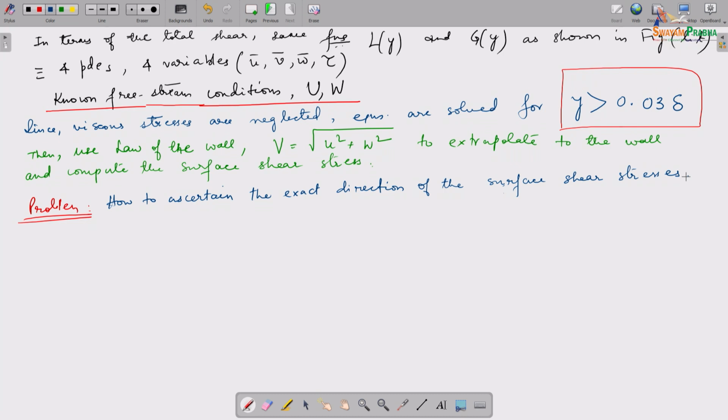Okay, so what do we do? Well, this is typical of CFD problems. We have issues with this kind of thing at the boundaries. We discretize, and say we're using a central difference formula, this is a finite difference problem, then one of the points will fall outside the boundary, right? That can happen on the left boundary or the right boundary. How do you handle it?